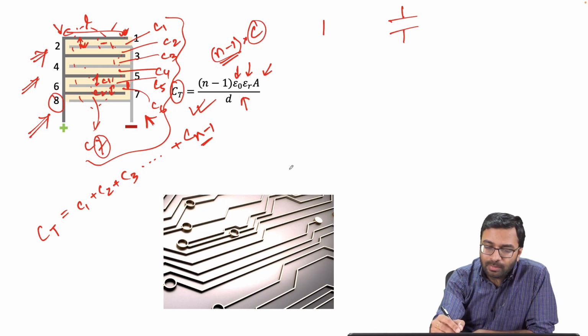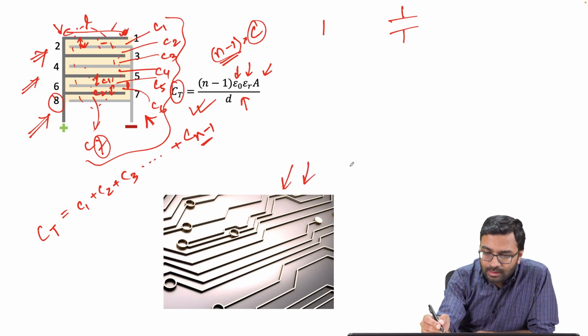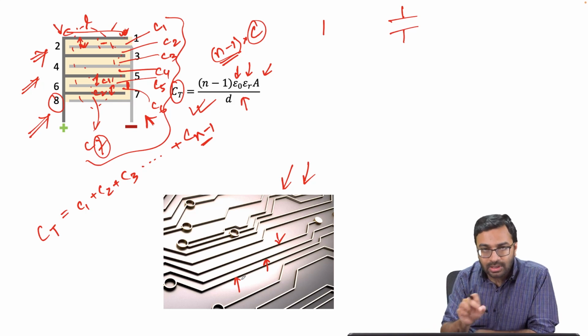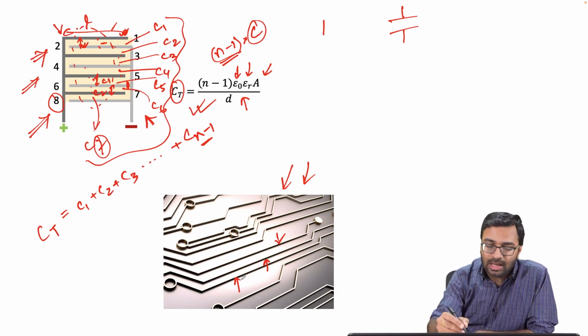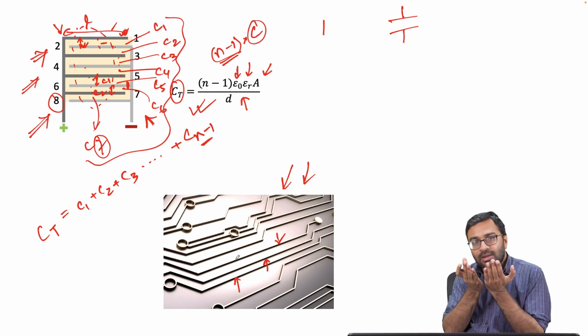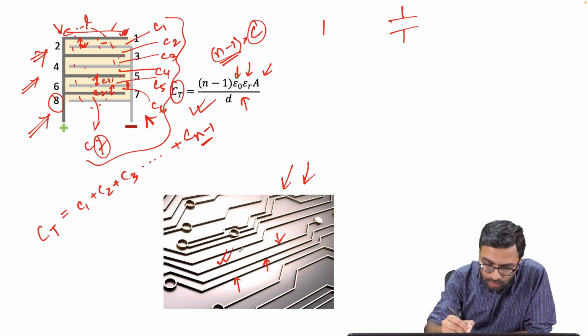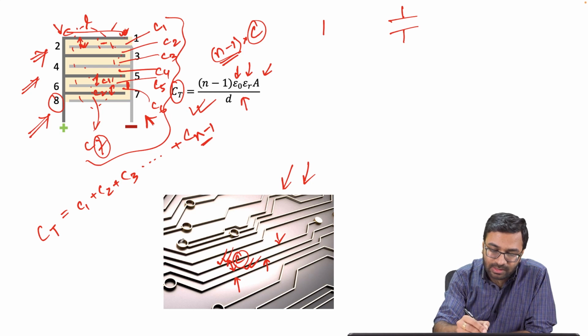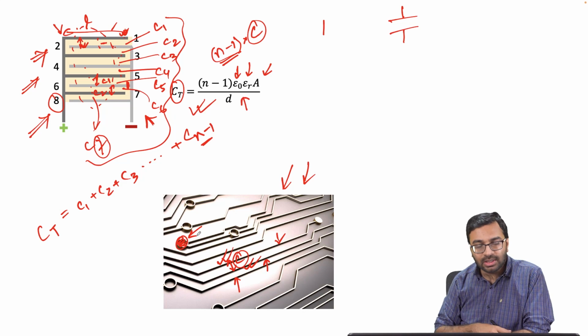Similarly, say you make a PCB circuit. In printed circuit boards, the lines associated with the connections or interconnects are parallel to each other and very close by. In that case, these two tracks will create a capacitance, and this capacitance may affect any other capacitor present, or will add to the capacitor which is connected to the circuit.